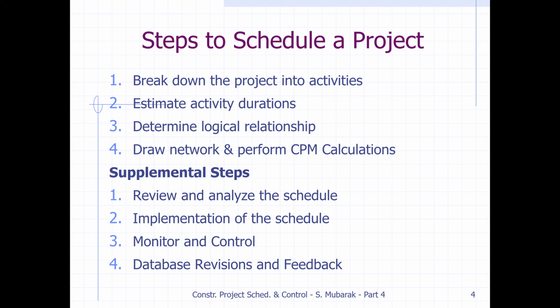To prepare a schedule, we need to break down the project into activities. Say for example, the foundation is one activity. Construction of the pile cap is another, then construction of the columns is another activity, then the cross head.